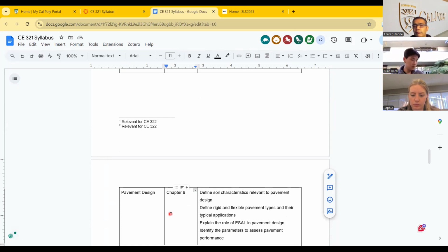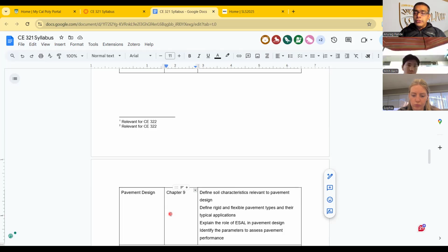And then I think the main thing that we learn in pavement is figuring out what type of truck loads we should be designing for, and then being able to estimate what we call the equivalent single axle load. So how much load is the pavement going to be subjected to? And based on that, in future classes, you can learn about what the thickness should be, what type of pavement should be put in there, how do we design that pavement? So all of that can come later. But in this class, you'll be figuring out the key design element, the equivalent single axle load. So estimating that.